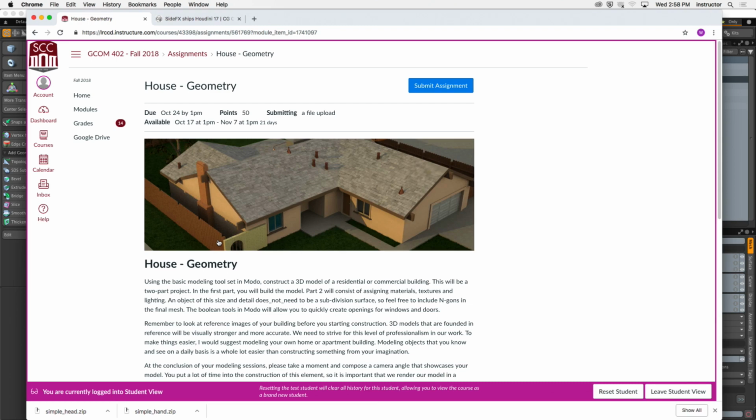It'd be pretty difficult to slice in 3 separate windows and ensure that they're identical to each other. It's really easy for me to make one and ask the computer to automatically subtract the other 2 from the wall using Booleans. So we'll talk about the role of Booleans inside of our modeling pipeline.